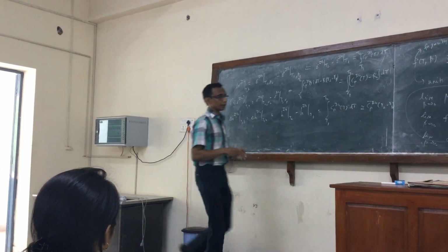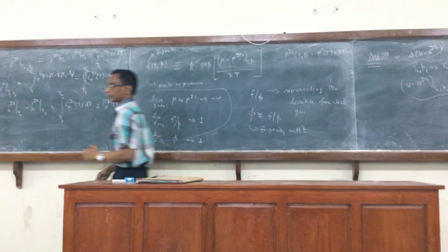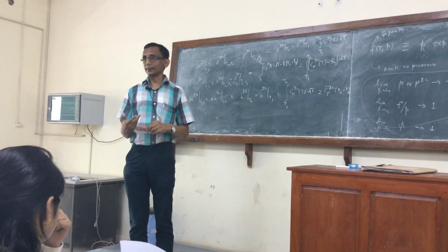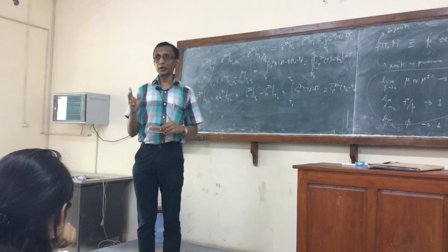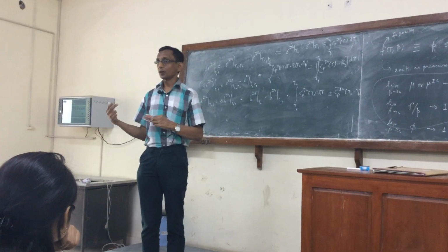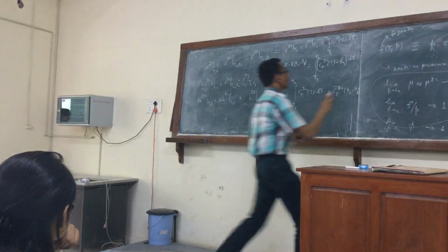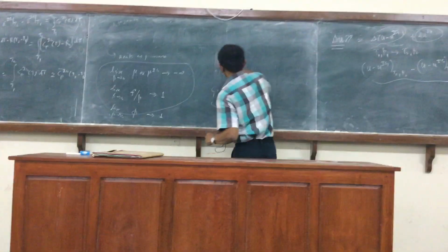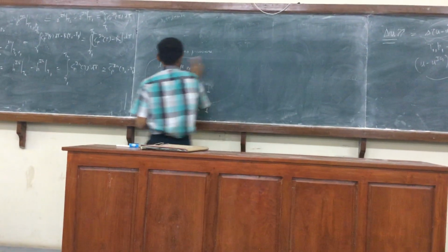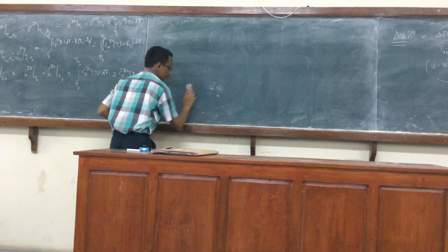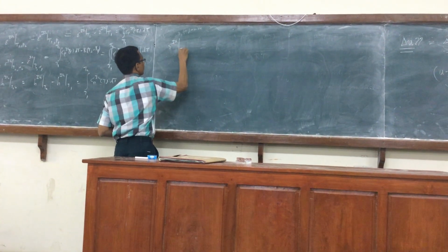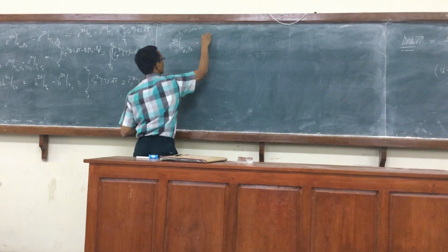Now, what about the other quantities? Entropy is slightly more involved because the entropy of the ideal gas is a function of both temperature and pressure, and as a result, the change will depend on whether T and P is specified or T and V is specified. Let's now do that, and let's first take where T and P are specified.